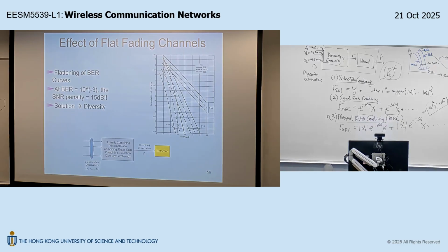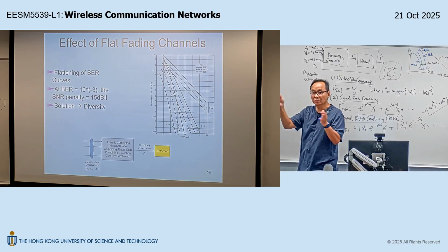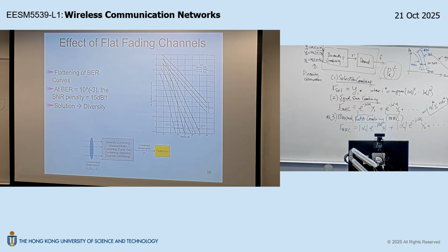This is called a header. This header contains information about the modulation level, the payload length, etc. And then this is a payload, the passengers. And then this preamble does not contain any useful data. These preamble symbols are just the reference symbols. Assume they are all 1. So you have n such preamble symbols. Now in practice it's not 1, but for easier explanation, let's assume they are set to be 1, okay? And you have n such symbols.